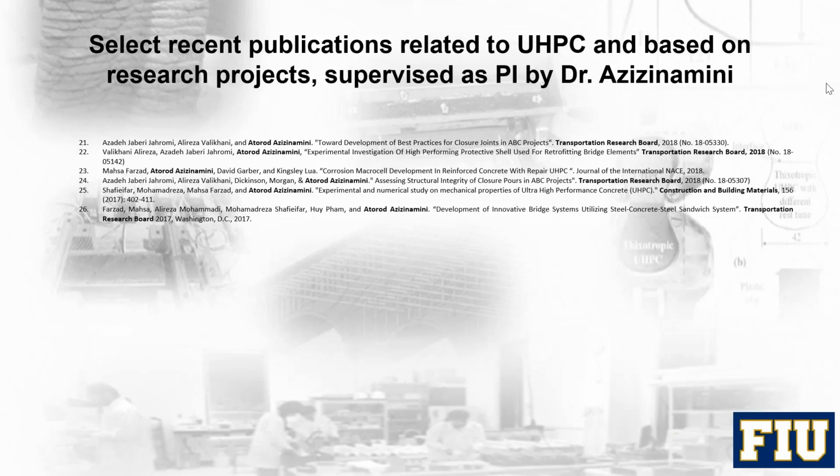Now, another problem that we have not addressed, but are working on, is the placement of normal strength concrete against UHPC, or UHPC against UHPC. That's a totally different problem than placing the UHPC against the normal strength concrete. The most practical problem we are dealing with is placing the UHPC against the normal strength concrete. There, if you get an exposed aggregate and make sure that the surface is wet, then you'll be just fine. All the test results indicate the interface stays perfect, and the failure is outside the interface.